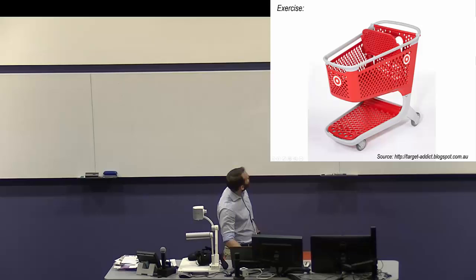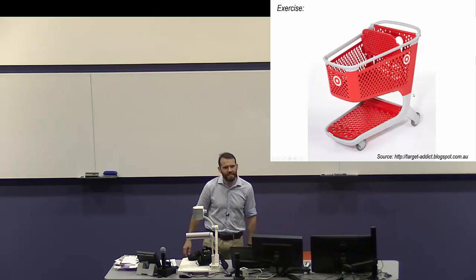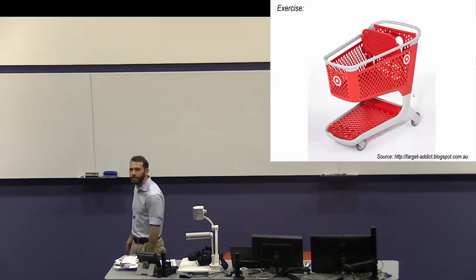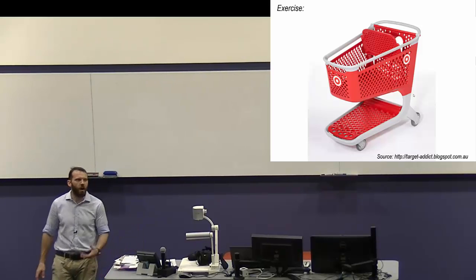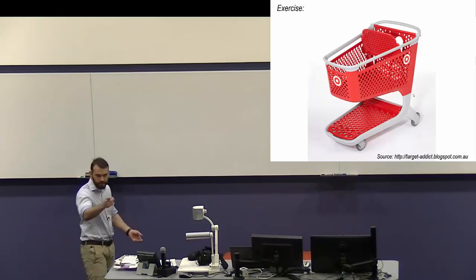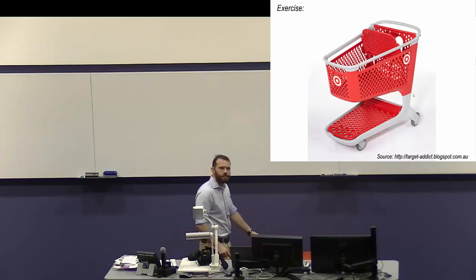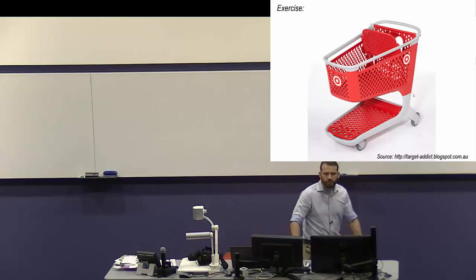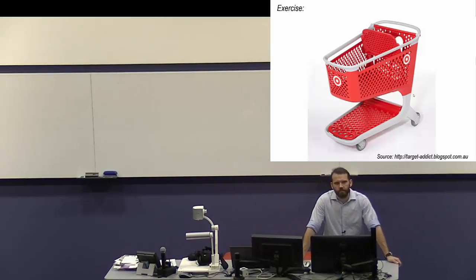That's obviously a join between two colours. Could that snap there, or is that a structural weak point? It's certainly going to be the highest stressed part of the whole trolley. Using plastic, over time the strain of your annoying little kids jumping in the front of your trolley is just going to snap it real quick. Potentially, yeah. Now I suppose that requires the engineering to be done on whether this would last longer than steel, because steel fatigues as well.